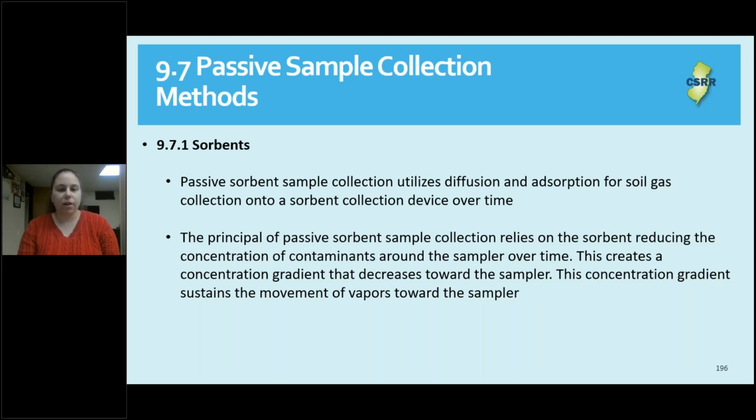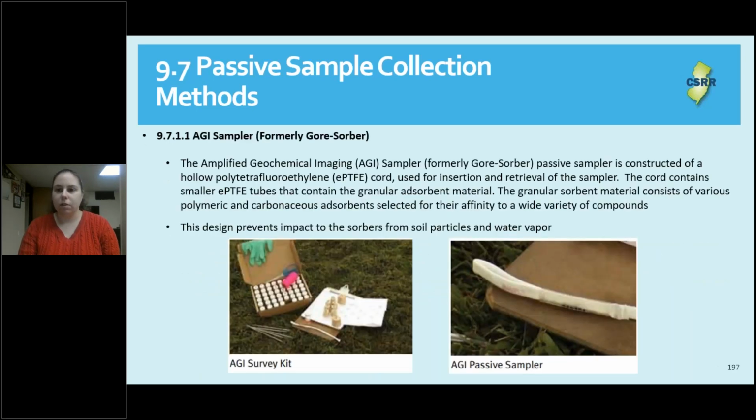This method, as Tyler stated earlier, should not be used in place of groundwater or soil sampling, as further investigation should still be performed. Passive soil gas surveys, however, are a good screening tool. Next slide, please.